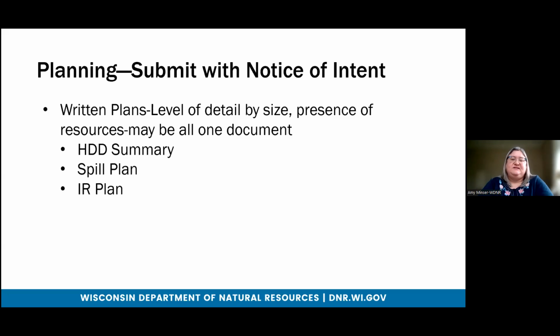Different utility companies have standard procedures, and where we don't need site-specific information, those can still be used. But we're looking for a summary of the HDD operations, a spill plan, and an inadvertent return plan.